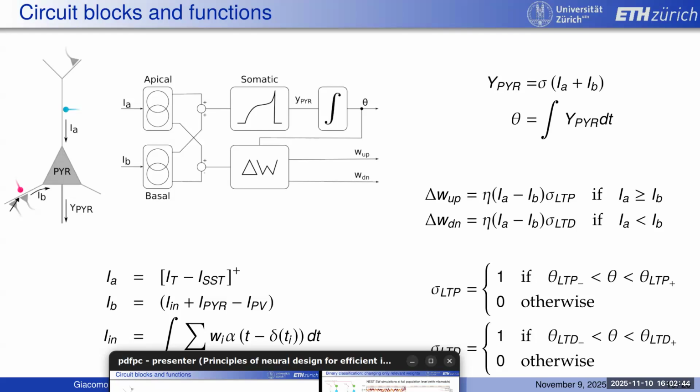And it only does that if you have enough calcium activity, which is coming from whether you have the SST blocked or not. So this is like a third factor. This is a Hebbian term. You have a learning rate, and then you calculate the difference, pre and post. And then there is a third factor which says stop learning or allow learning. And all of this, as I told you, it's basically 5-6 transistors each. It's really, really easy to implement this using this Carver Mead type of approach.